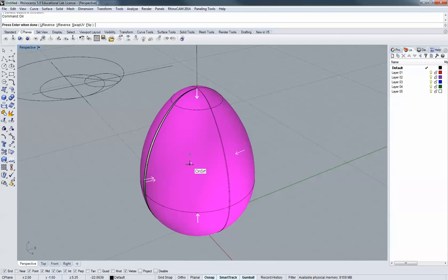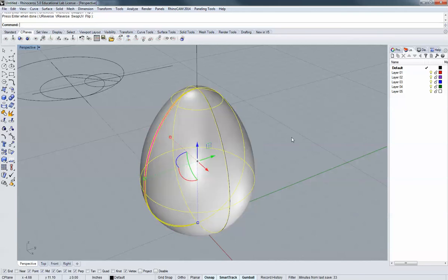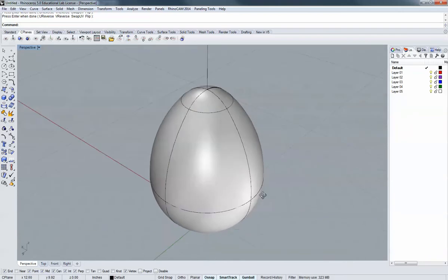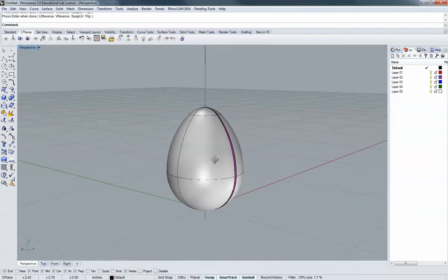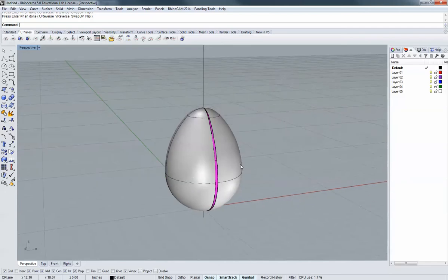So the simple thing to do is just to click on the object, and it will flip all of the faces so they're facing the opposite direction. And then if we go ahead and hit enter, it solves that problem. So at any rate, the reason I wanted to do this first was to show you one of the important steps in, I'd say, proper model craft, particularly for 3D prints. You cannot have any what they call naked edges.